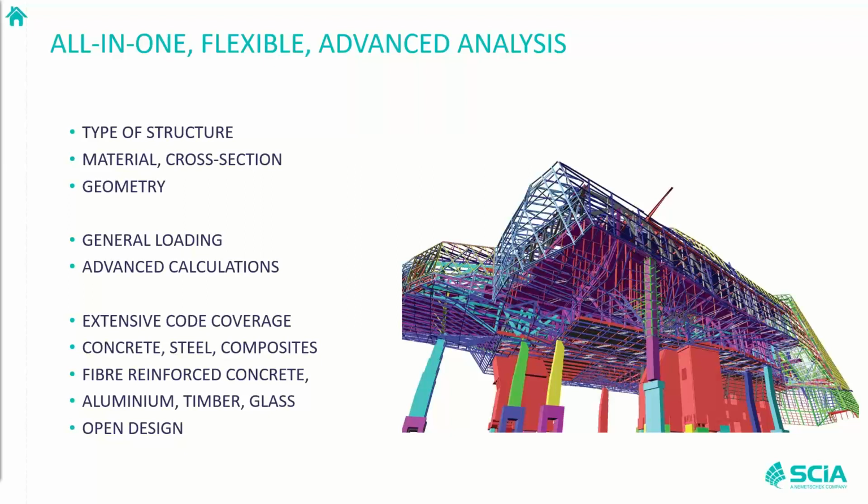For loading conditions, there are many possibilities, including free forces, thermal loads, load panels, soil pressure, snow, wind generators, and more. For advanced calculations, finite element mesh is generated in the background and features automatic refinement for selected load cases. There is optional manual refinement along a point or along a line. Other analysis studies include static linear analysis, local nonlinearity, and geometrical non-linearity for initial imperfection and second and third order calculation. Material non-linearity for masonry and plain concrete is possible, as is plastic analysis for non-linear material behaviour for 2D members. This can be combined with other non-linearities in SCIA Engineer.